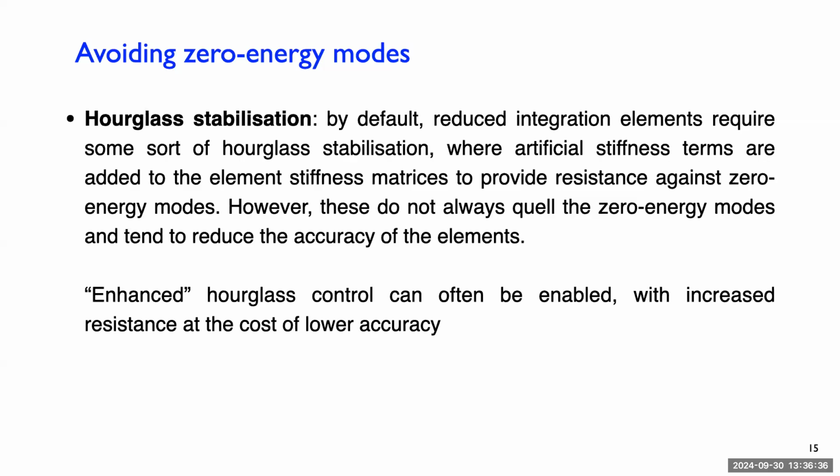So that can work okay. It can quell those zero energy modes, but it tends to make the elements less accurate. It's kind of like they're adding a smoothing term to stop the elements being so deformable. So it is a balance and it's hard to get that right. It's a bit ad hoc, but this is what's used by default and it works okay, but sometimes you will still get zero energy modes. Sometimes it doesn't work.